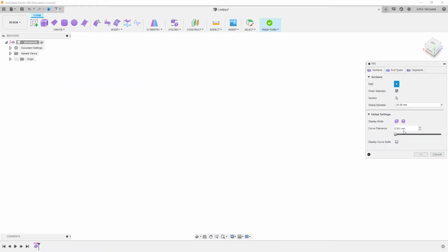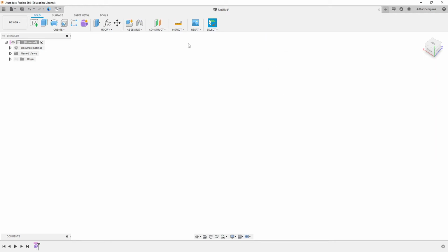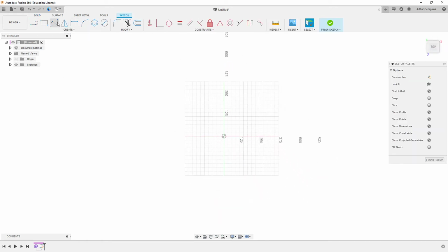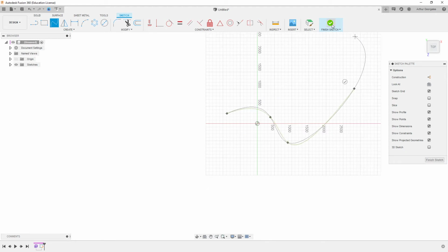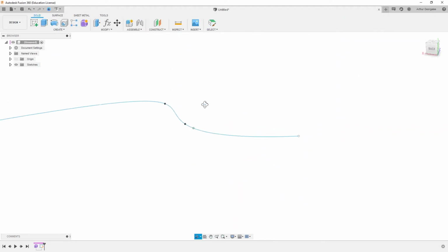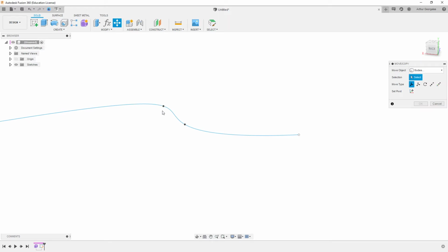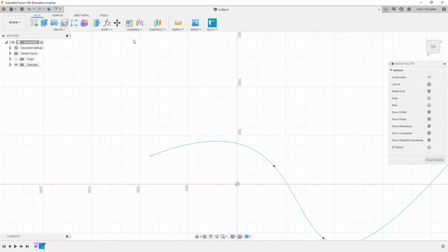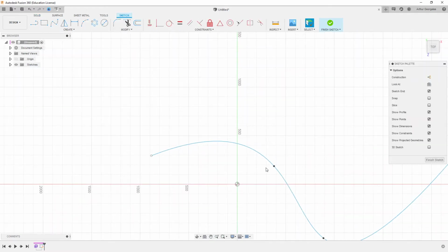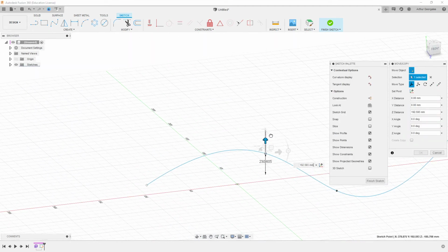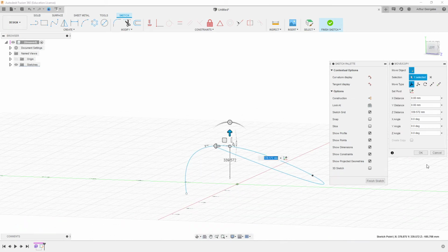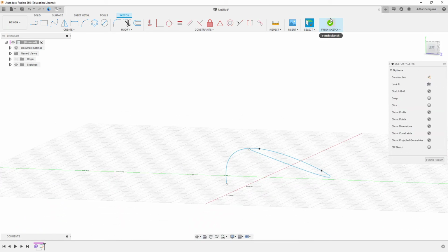This actually requires a path. So you can do the pipe command in two ways. You can sketch something in the standard modeling workspace. So I'm just going to go ahead and do something like that. And when you're editing the sketch, you can use the move command to pull it out into 3 dimensions as well. So we'll do something like that, and we've got a 3-dimensional sketch.